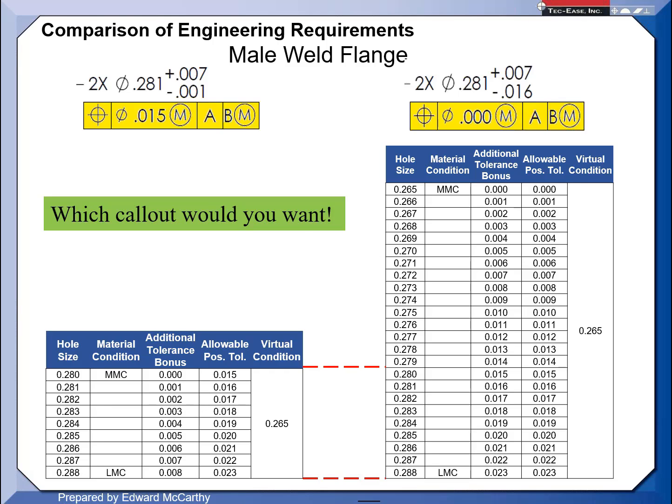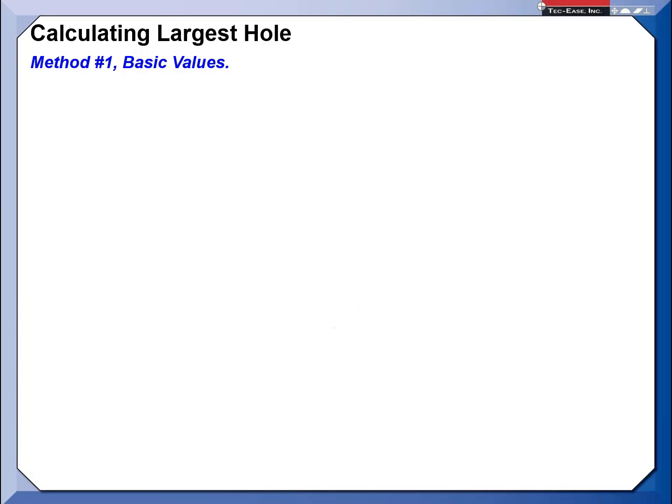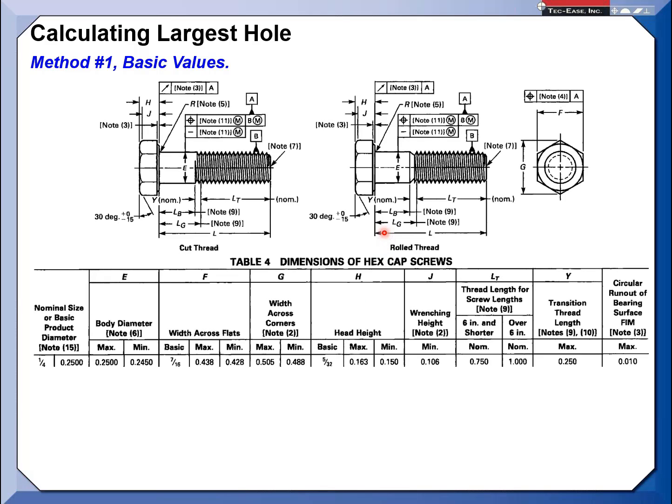So we're dealing with the bolt here. With this chart here, could you say that one more time, Wendy? Yes, it says, is the bolt head width F assumed to be the same size as the round contact face under the head? Oh, okay. So F here is actually controlling, you'll see it across the flats. So yeah, in that case, they are assuming that they are the same.